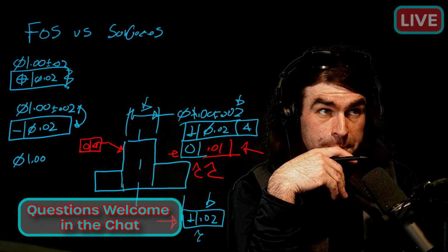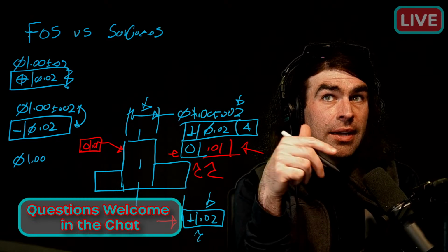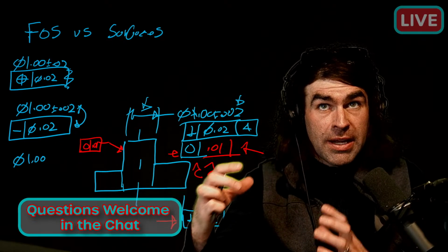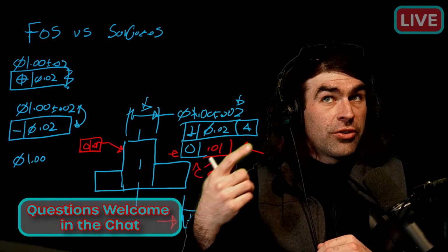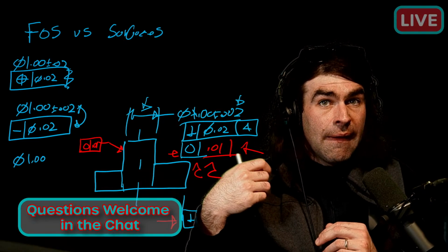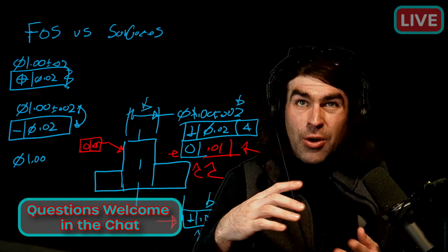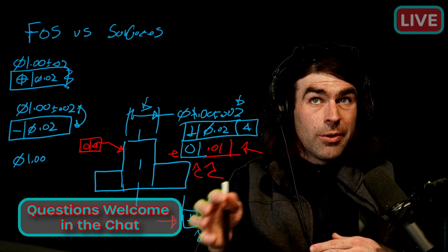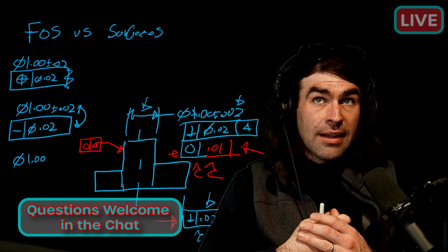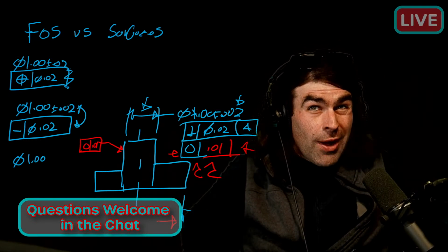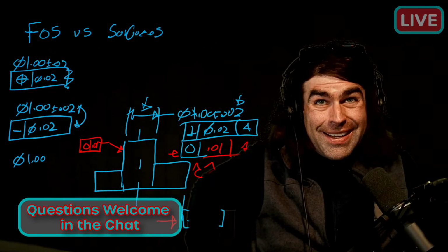Runout is going to help you with anything spinning quick, because when they go check it, they're going to make sure it's coaxial. They're also going to check the form around the outside. So you're going to get something that's not totally balanced, but pretty close, right? It's a very functional check for things that are going to spin. So I would definitely lean on runout for things that spin like that.